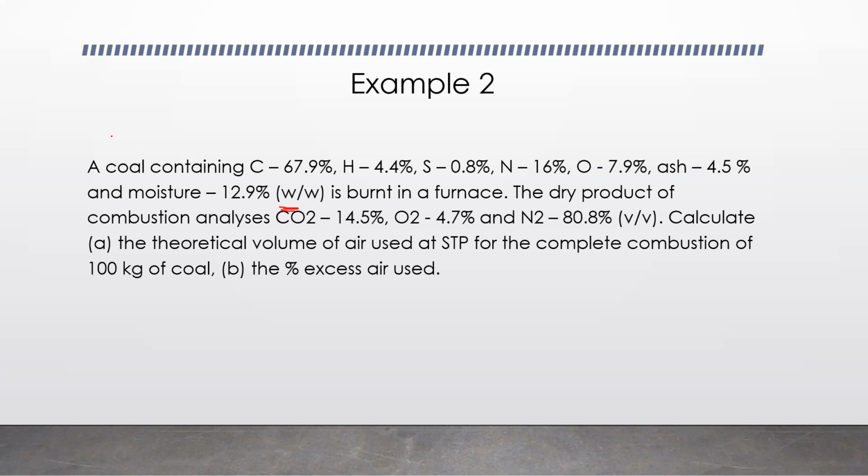Remember, usually for solid fuels, all these percentages that are given are by weight. The composition of a solid fuel is usually given in terms of weight percent. And when we talk about gaseous fuel, and sometimes a liquid fuel, it's usually in terms of mole percent. But for solid fuels, even if it is not mentioned, you can say that it's weight by weight, unless and until it's given that it's volume by volume or mole percent.